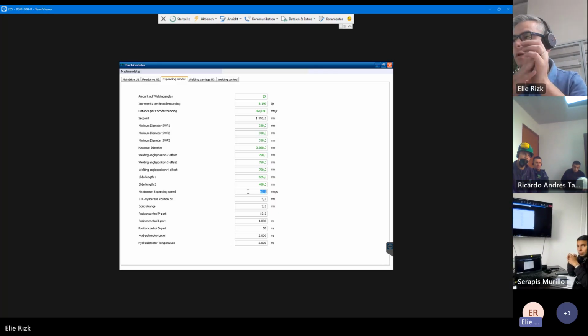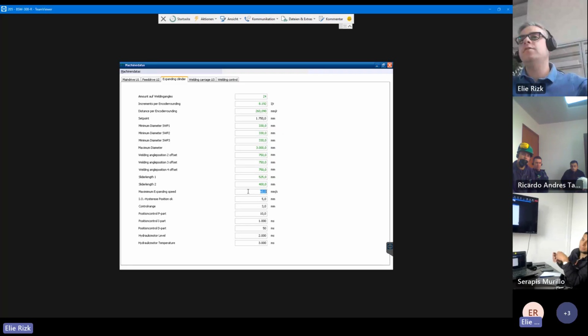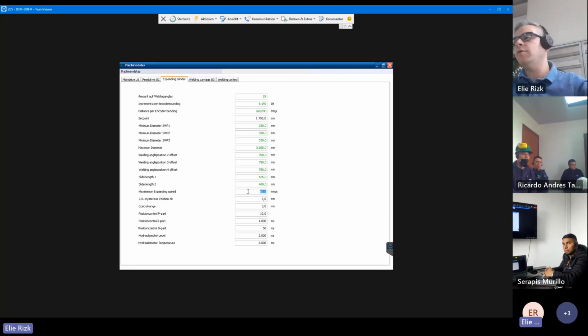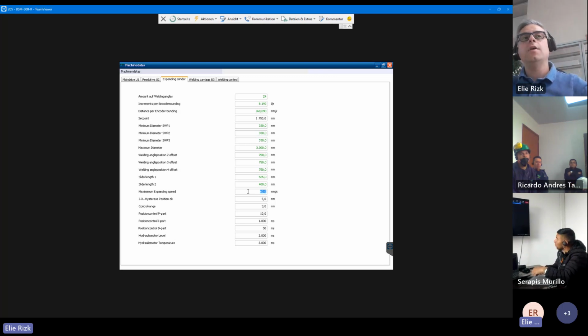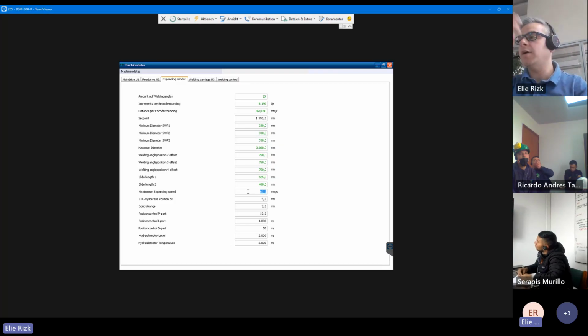We always say what the actual position is for the diameter. So you measure it, you say, okay, I have one meter, then you enter it in the set point. If you are on position 1, you enter it as is; if you are on position 3, you deduct 750, then you enter the number and say start. You go to adjusting and press start and the value will be taken.